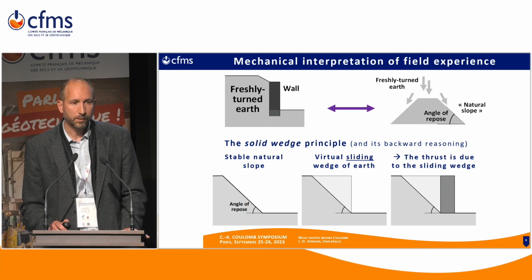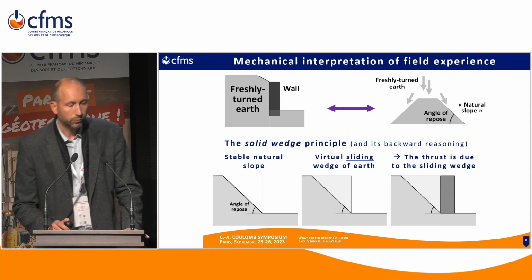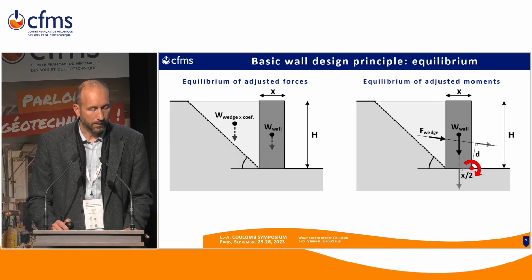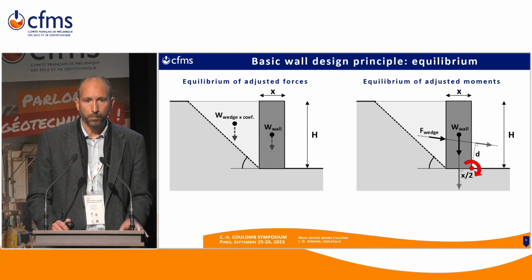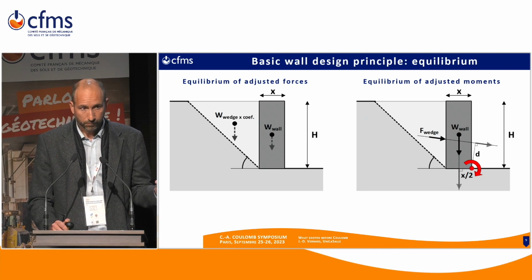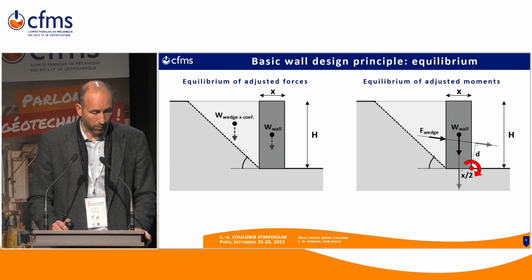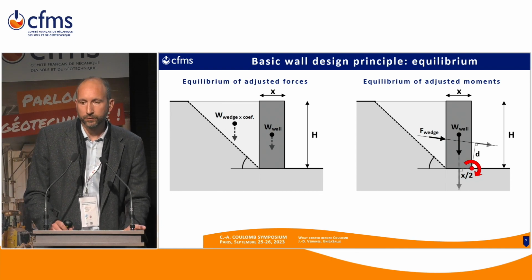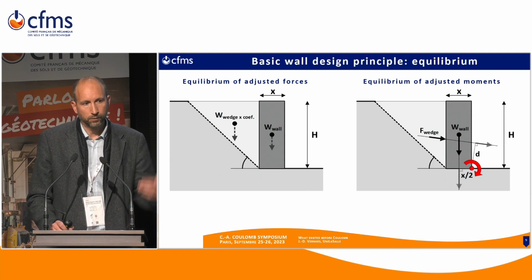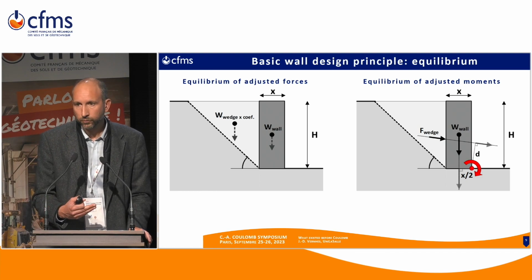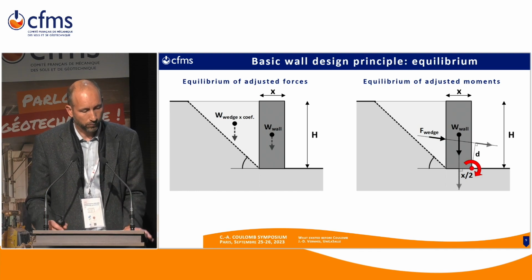Whereas another principle Bullé has used was soon outdated, and this is the way he had built up his design model, because he used the idea of adjusting forces, so in fact only the weights of the wall. And if you consider, for example, that the wall is based on a ground with a 45 degrees friction angle, it's equivalent to consider the vertical force, which is the weight, or a horizontal reaction. It's just balancing those forces.